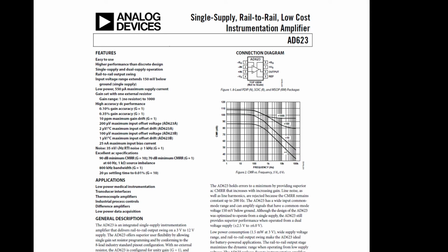So you can see that with a bit of knowledge of the thing you're trying to measure, an understanding of your sensor, and some basic signal processing ideas, you can start to build the bare bones of a system that might actually do the job you're interested in. But then we get a choice of, well, what kind of amplifier are we going to use? We've said we wanted a gain of 10 or so, and we said it was probably a differential signal that we're interested in. How do we do that?